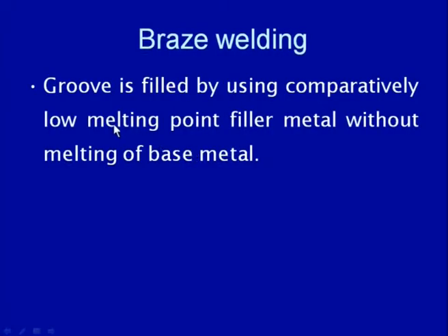But as far as similarity with brazing is concerned, only melting of the filler material is done, and melting of the base material is not done intentionally for developing the weld joint. So, the advantage is that the heat is not much applied to the base material and only melting of the filler material takes place. Once the groove is prepared between the plates to be joined, the groove is filled using comparatively low melting point filler material without melting the base material.